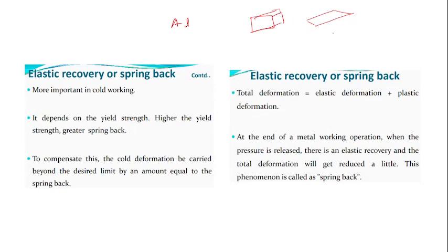We know that spring back will be more in the sheet. Now the material is the same, so the elastic modulus will be the same here and here, right? It depends on the moment of inertia. Spring back.